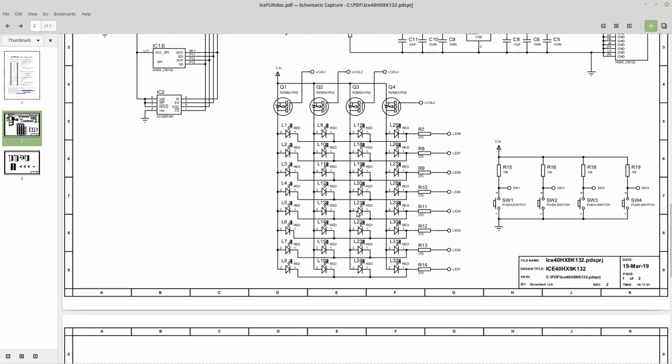So in fact, just L21 will light up. The column drive is a PMOS FET, and that transistor will turn on when its gate is at ground level, because that will turn on, and then this will be at 3.3, and that will light up the LED. So LED 4 is going to be the drive that will flash the LED. Column 3 will be permanently low, just to light up that one LED.